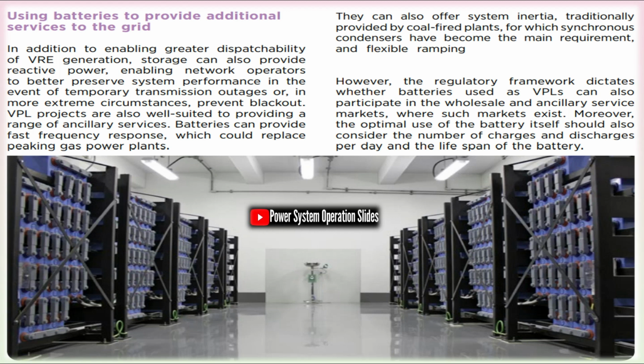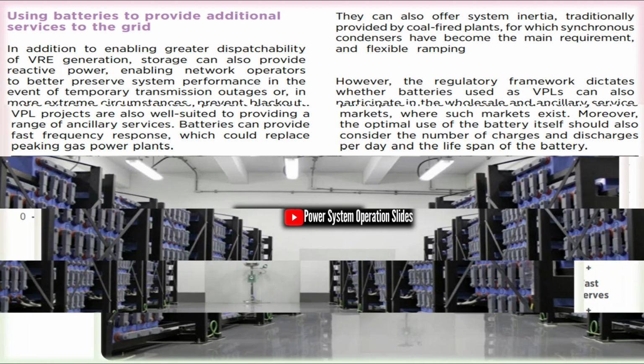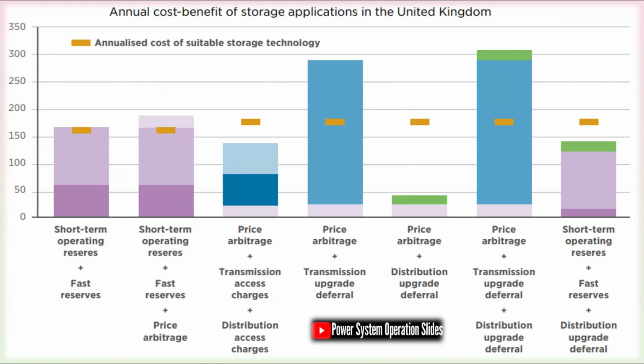Disadvantages and risks. Limited capacity compared with a new physical line. VPLs can increase apparent capacity only up to physical and stability limits. They are not a literal replacement for a permanently required corridor. Dependency on communications and control: requires high-quality telemetry, low latency and secure comms. Failures reduce effectiveness or create risk. Cybersecurity exposure: more digital control surfaces increase attack vectors.